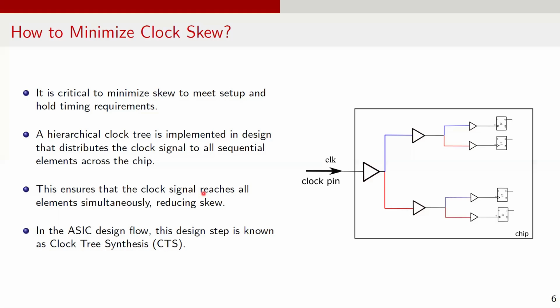thereby reducing clock skew. To achieve this, buffers and inverters of various drive strengths are strategically inserted along the clock paths. These components help balance delays, compensate for parasitic effects, and align clock arrival times across the circuit. There are specifically designed clock buffer cells available in the standard cell library for this purpose. The ultimate objective is to minimize clock skew so that all related flip-flops are clocked as synchronously as possible, preventing setup and hold violations.